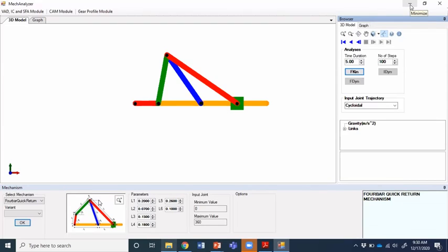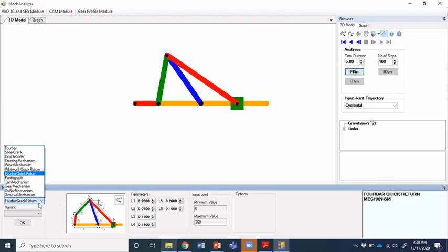So these are different examples of your 4-bar mechanisms and different linkages, and it's up to you what kind of motion you want to achieve from that. So for that you have to just do the analysis. So first you will do the analysis. Okay, if you have particular kind of mechanisms, you can get particular kind of motions from there. But if you want particular kind of motions, for that you have to do the synthesis, means what kind of design or what kind of graphics or what kind of dimensions your link should have, which link you want to extend to get particular kind of motion.